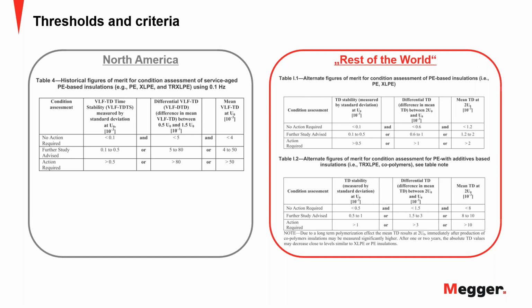And the preferred monitored withstand test, which is the latest hot topic, is you do the VLF to have your safety test. If you switch on, it's not going to explode or fail. And you monitor the PD activity. Let me share one more slide for this last question.